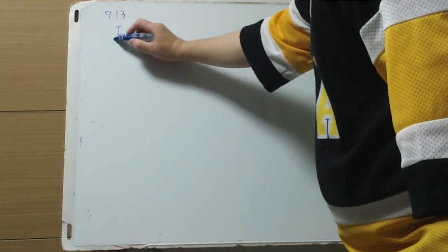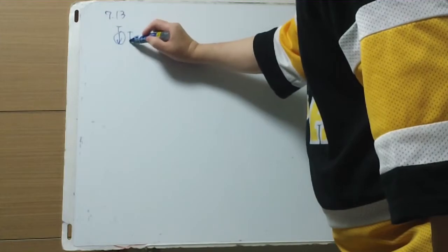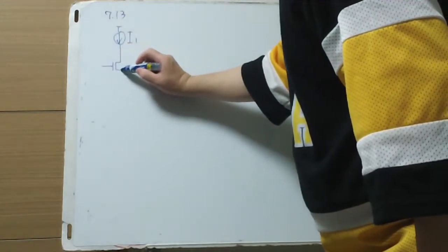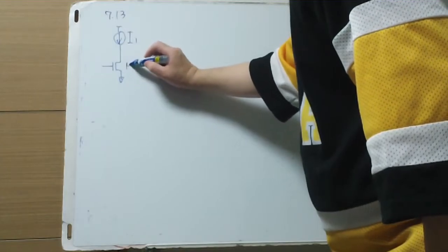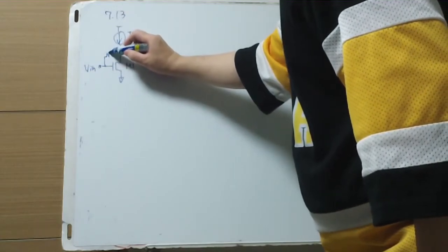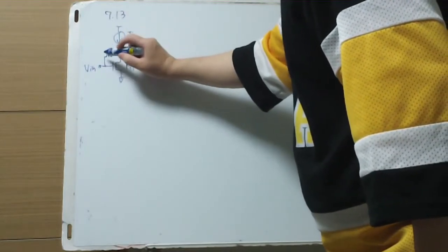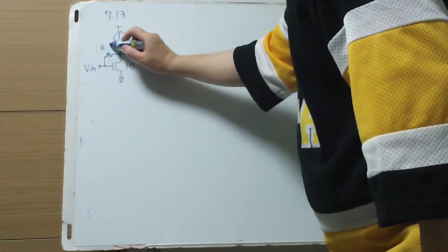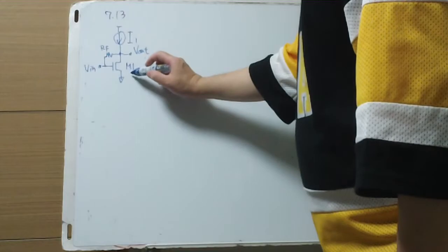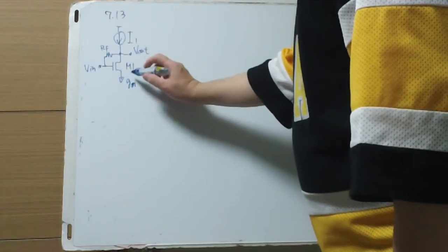there's a VDD up here, and an ideal current source whose current is I sub 1, and the input transistor NMOS M1 is there, and V in is applied there, and it is fed back from V out here, and the feedback consists of a resistor whose value is RF, and the NMOS has a geometry producing transconductance gm.